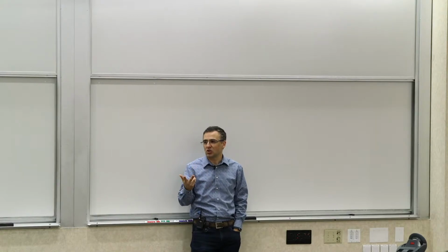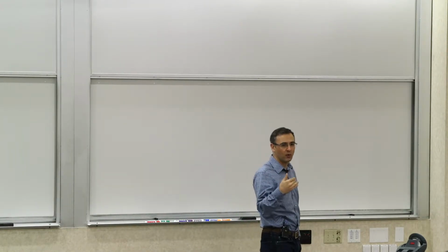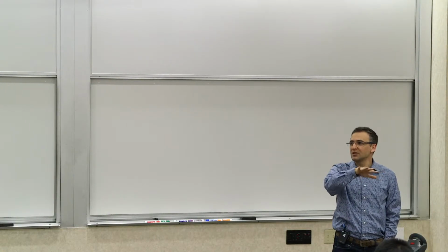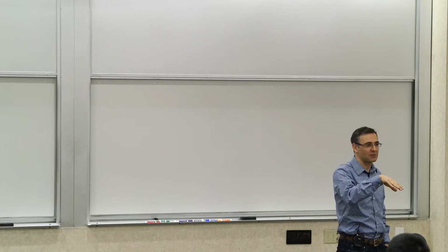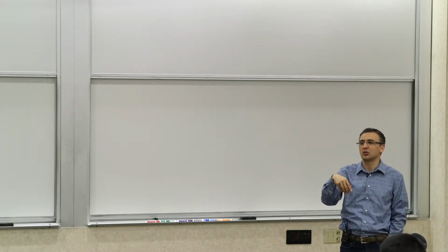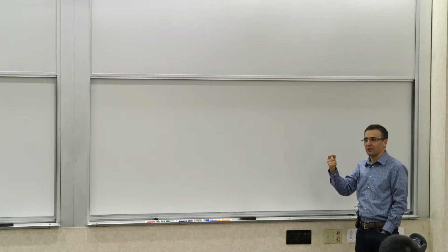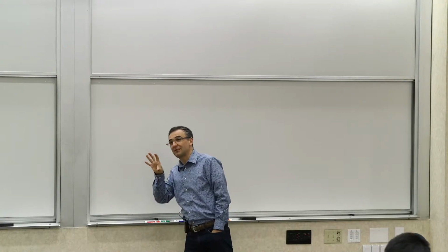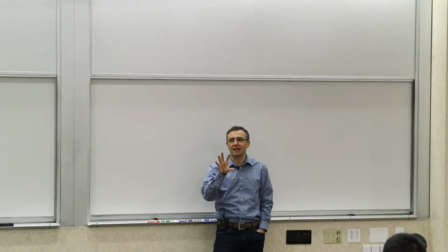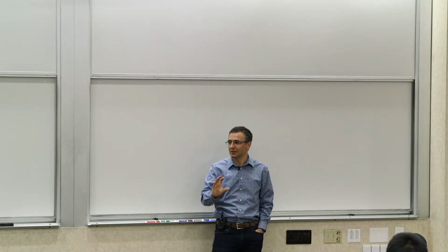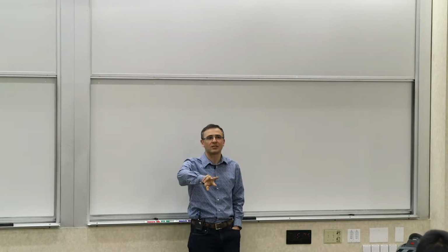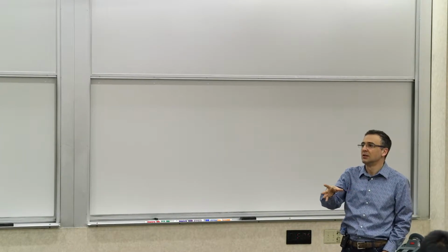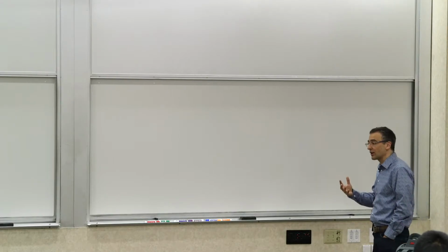And one of the things that we saw is that if you had dynamics in the forward path, in the gain A, that effect was kind of suppressed as long as your gain times the feedback ratio, AF, that product was large enough. And then we also looked at the effect of some dynamics in the feedback path, and what we saw there is that the transfer function got inverted. If it was a rational function, its poles became the zeros and the zeros became the poles due to the action of the feedback if you had a lot of gain.